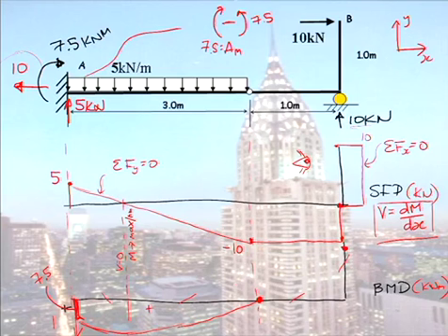Then my slope in here, it's 0 here, so it must increase like so. And then I move to the other end. My bending moment is 0 here, so it must slope down. Now can you imagine that corner, see my two arms, flattening out? If I opened up that corner, would that point there join up with that point there? Yes, they would touch.